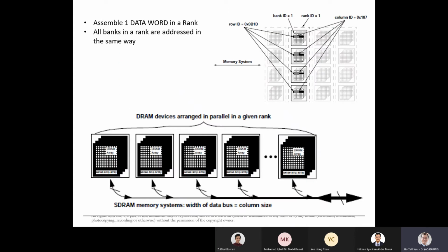Now it's going to get more complicated. Within one chip, there are multiple banks. But as I told you, within one bank, there's times 4, times 8, times 16. That's only 16 bits. Nobody builds a 32-bit bank. So in order to get 32-bit banks, you need to group 2 16-bit banks or 4 8-bit banks together. You got it?